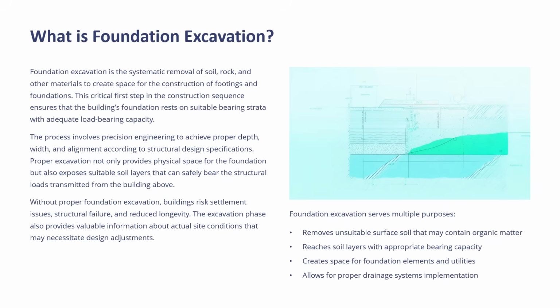So it serves multiple purposes: it removes the unsuitable surface soil that may contain organic matter which may affect the building, it reaches the soil layers with appropriate bearing capacity over which the foundation will rest, it creates space for foundation elements and utilities, and it allows proper drainage system implementation.